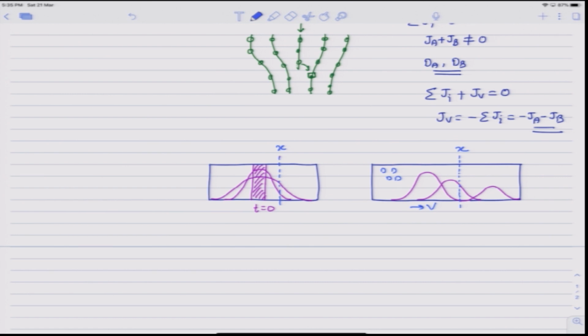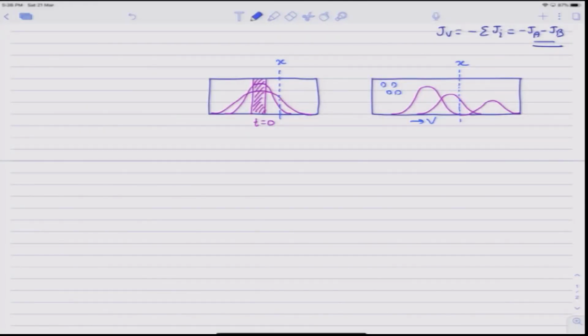In the same fashion, we need a marker which can stick to the lattice plane and which is stable at the diffusion temperature, which means the marker should not diffuse in the matrix and also it should not react with the matrix or with the other diffusing elements. And that can be done if we place these markers on the initial contact plane before we sandwich the two alloy blocks before the start of the diffusion experiments.